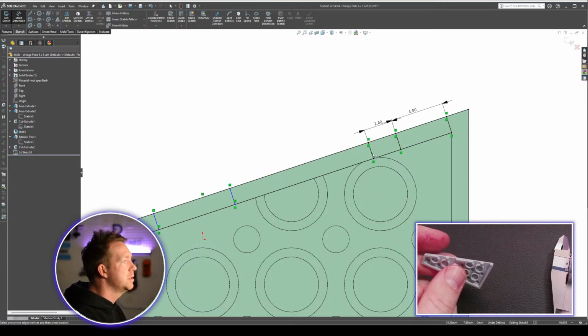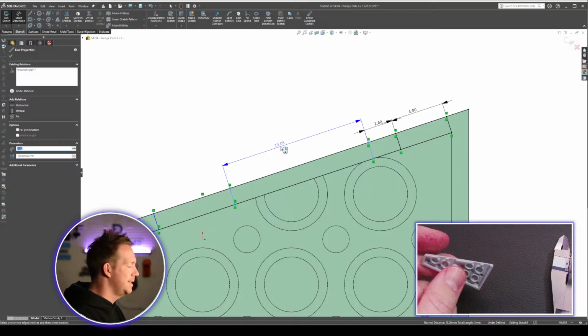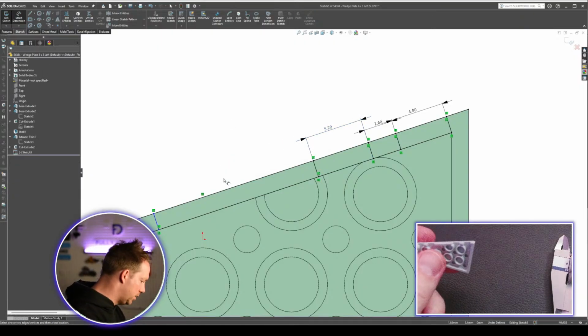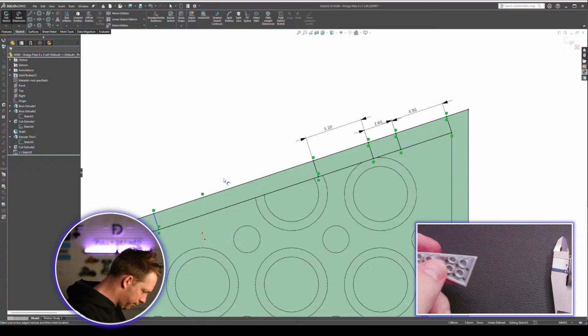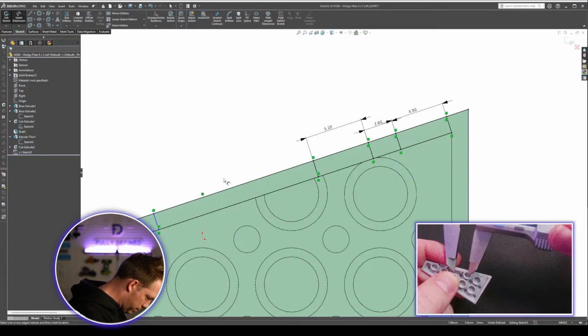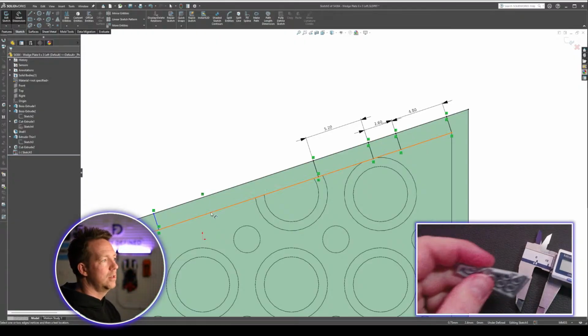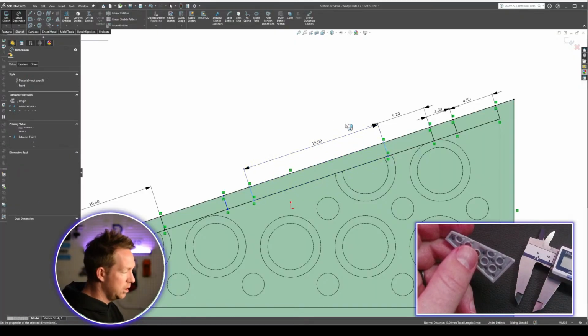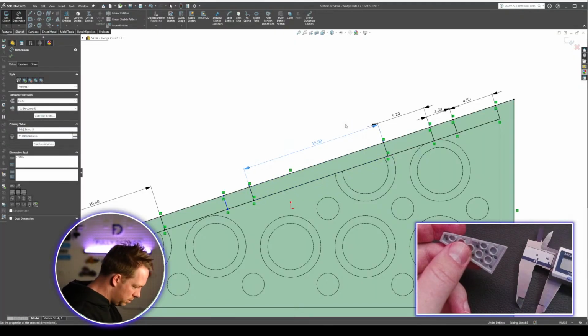Each of these dimensions is just going to help fully define and get the detail correct, and make it quicker for any changes to happen next time. That's why the fully defining is so important, because even if you don't get the dimensions right the first time, it's such a quick change next time round.